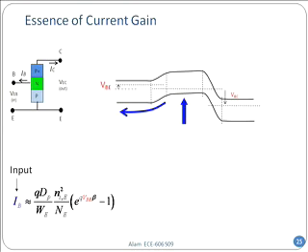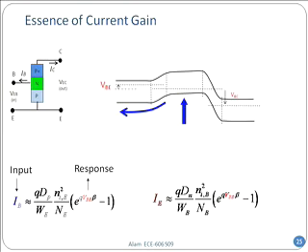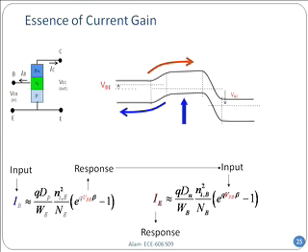Now, when you force a voltage in response, it forward biases the junction, and the electrons, which are just sitting there, say, well, my barrier is lowered, so they decide to go on their own. So now you can see, for electrons, the VBE becomes the input because the barrier has been forward biased, so the current will flow. As a result, you can see that red arrow going from the emitter to the collector region. This is how the base current controls the collector current. This is how the gain occurs, right?